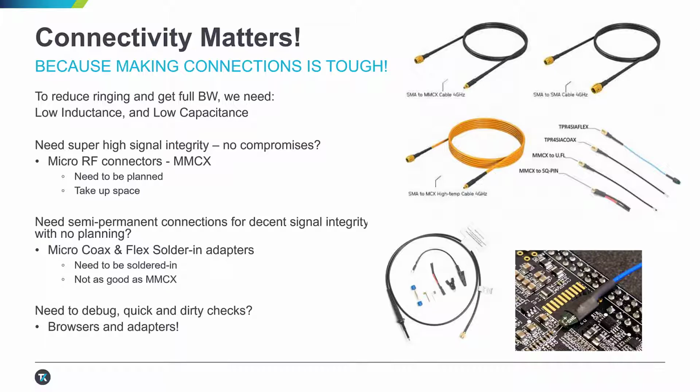and of course, the challenge with these is getting a good solder connection can sometimes be more of an art form. But for those that can, the solder-on tips are a good option for getting as close as possible. We offer some solder wire to get down to the nearest capacitor or whatever test point you're trying to solder down to. And just as long as the tips from that solder are not substantially long, we won't be inducing a significant amount of inductance into the measurement.